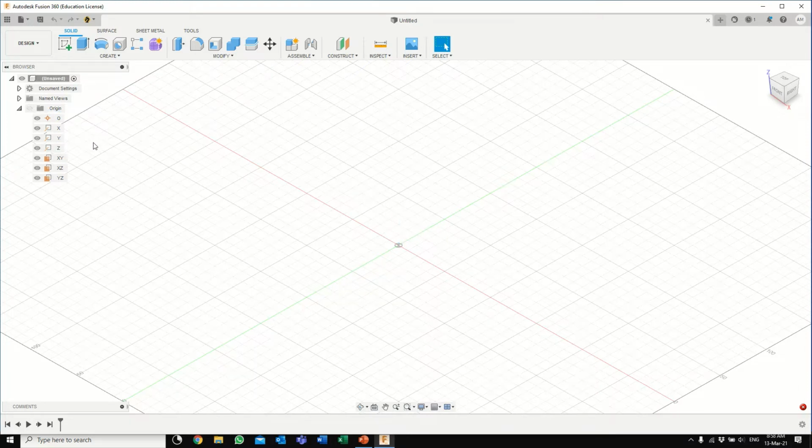Then we have the most important thing, which is the planes. These planes are important since for any 2D sketching, to start 3D modeling, you have to select the drawing plane or surface. So you either select here first and then start sketching, which is this button, or you sketch and select one of these or any other surface that you have already drawn.